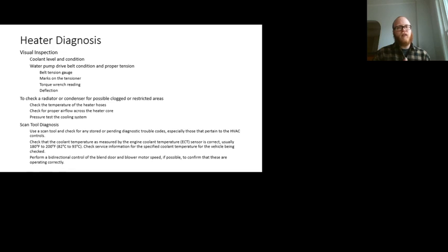And all the heat and the crazy stresses inside of an engine start to create the same conditions that rust happens in: electrolysis. There's actually electrical current passing through the block of the engine. Anything that's case grounded on the engine is doing that. All that can build up to a cooling system that's prone to creating this white, chalky substance as the aluminum of the engine breaks down. And then, even if it gets in with cast iron, it can start to turn a muddy or sludgy color.